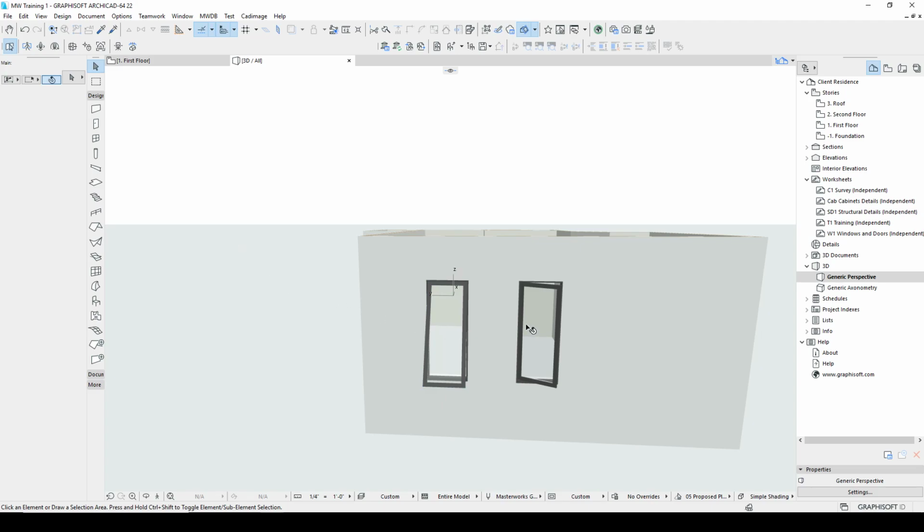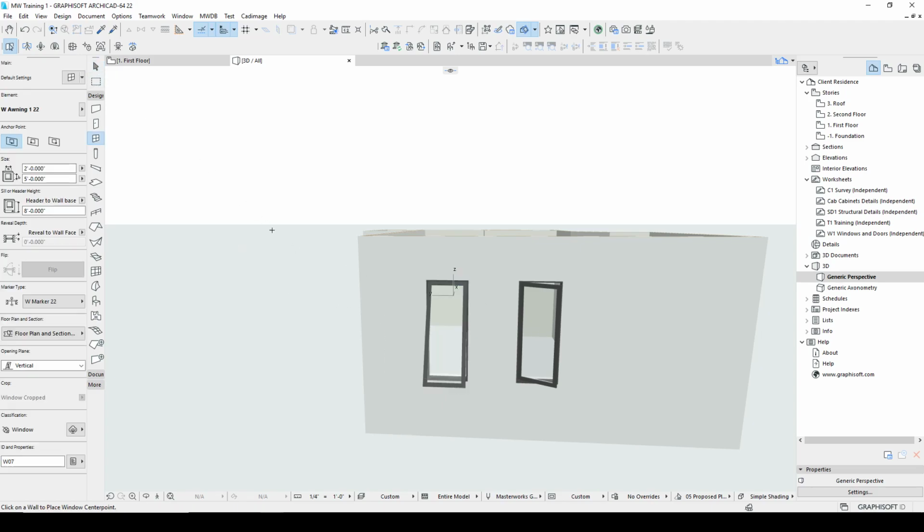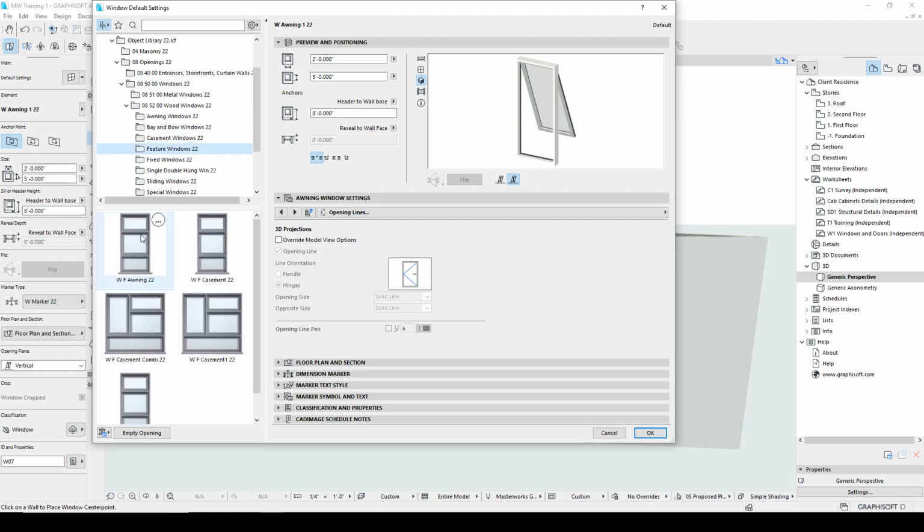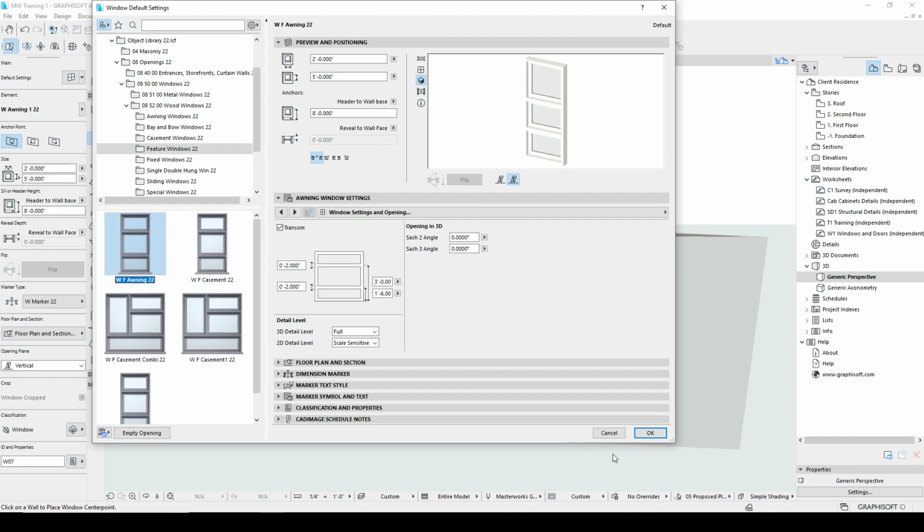And again, the trick is, if you're going to pull these in, don't click on anything because it'll revert to the default. You have to hit Control and paste it in first. Notice that it changed the size, it changed the header, it changed the materials. Everything became the same as the last window that I had the property from. So that's a really useful strategy to use.